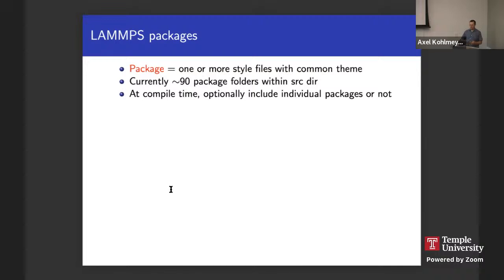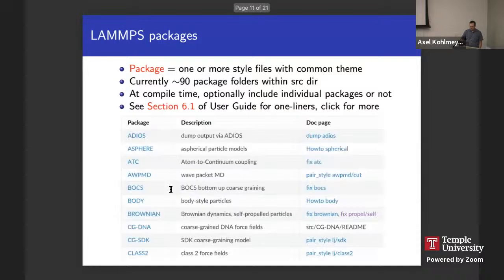Otherwise, you'll get an error that says pair style EAM is part of the MANYBODY package, which isn't enabled in LAMMPS. You can see in the doc page there's a one-line description of the different packages. For example, the BODY package is for body style particles. It has a doc page here.